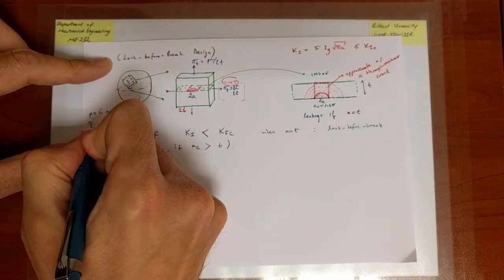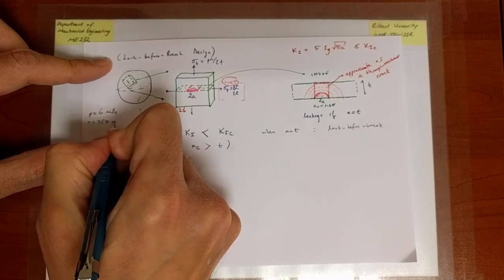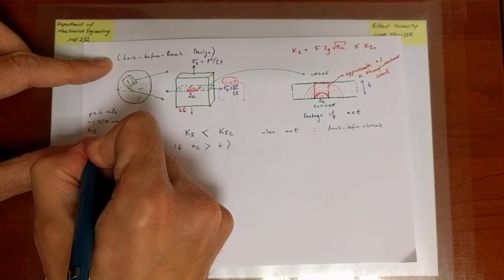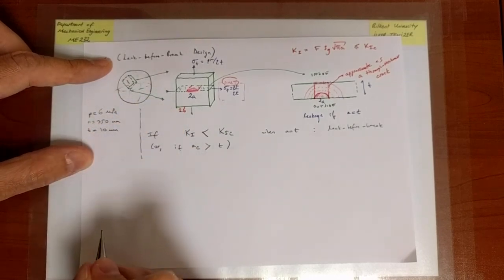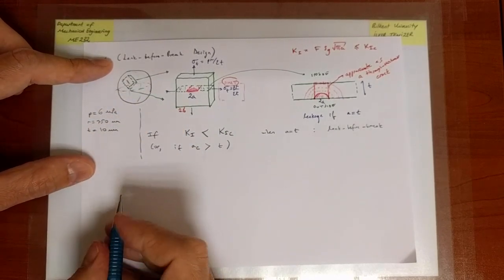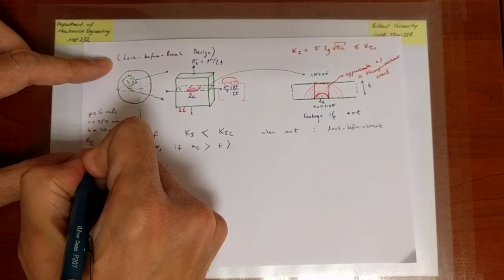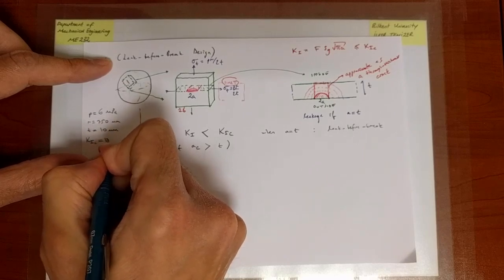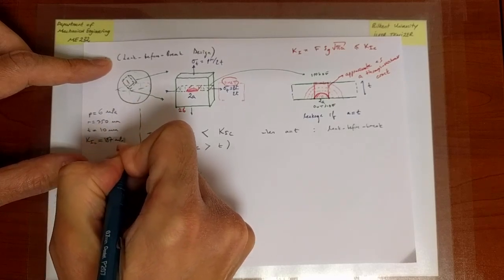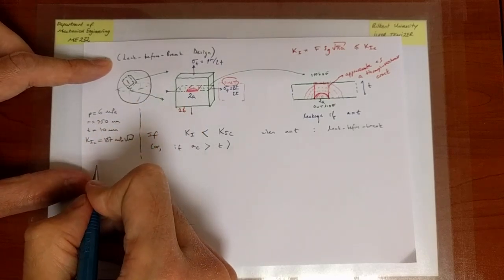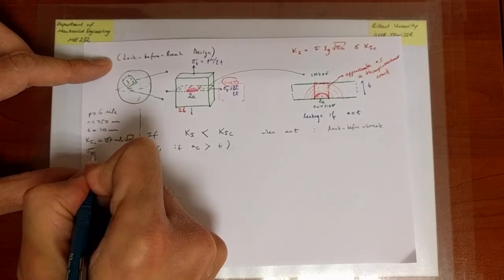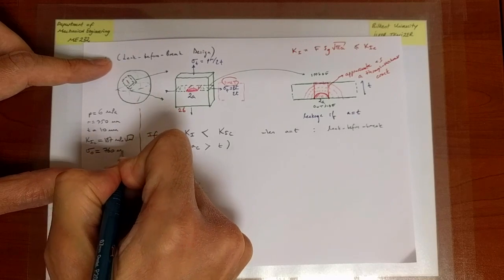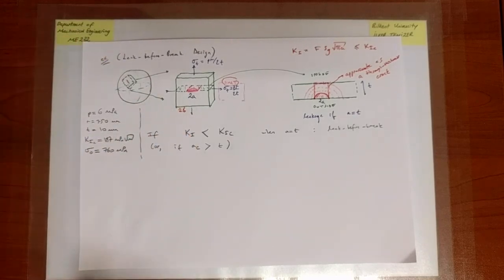The radius is 750 millimeters. Inner radius, outer radius doesn't really matter because the thickness is just 10 millimeters and it is certainly thin-walled. I do need material parameters. The fracture toughness is 187 MPa square root meters, and the value of the yield strength, which I will eventually need, is 760 MPa in the context of this example.